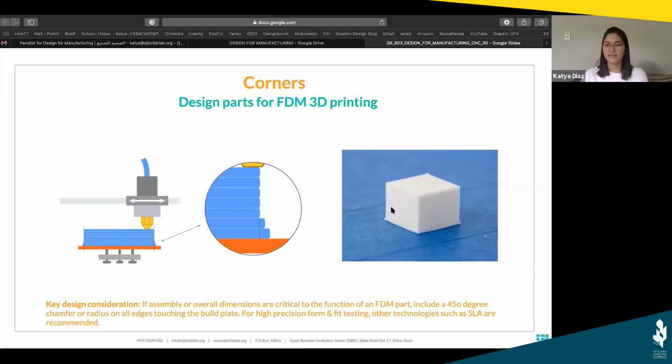We have to make a chamfer of 0.2 mm at 45 degrees. If we make a chamfer in here, then it will expand and reach a straight wall. So this is one way to correct this. This is actually called elephant leg, or elephant foot. So this is one way to correct the elephant foot.